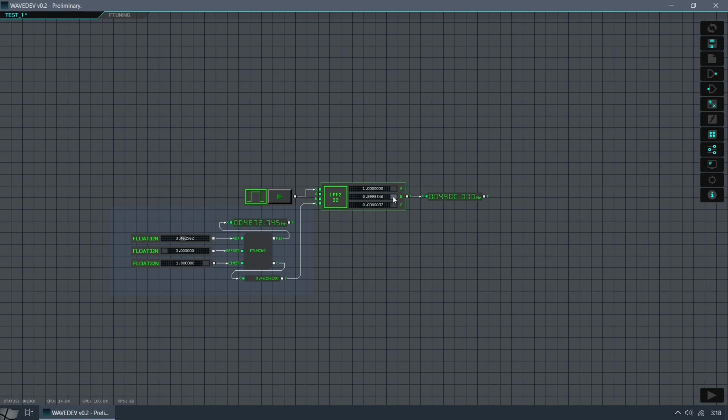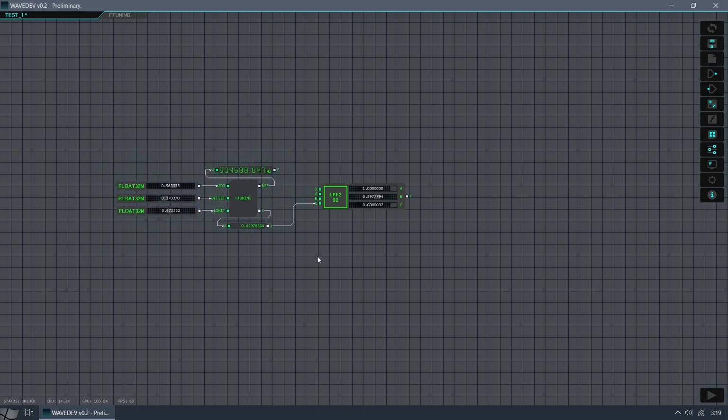Now it is no longer necessary to set the resonance to the maximum, and use a button with the frequency meter to measure or configure each filter. We can reduce the limits to select even finer frequencies than what the bar offers. Although it is not critical for this project. This is just an example of what we can do to compensate for the lack of some tools. The frequency reader will be included in the filter in future software updates. It is very common to create additional test functions to support specific projects.